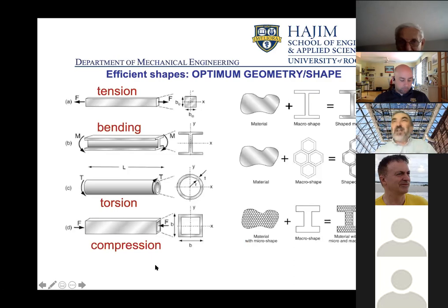So here we'll talk a little bit more about the technical side of mechanical engineering. When it comes to structures, everything boils down to 4 categories, namely things that can go in tension and break, things can bend and break, things can twist and break, and things can compress and fail. And when we look at engineering structures, we have essentially a background engineering material.